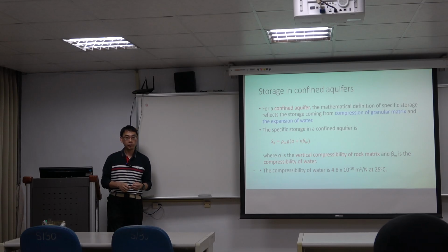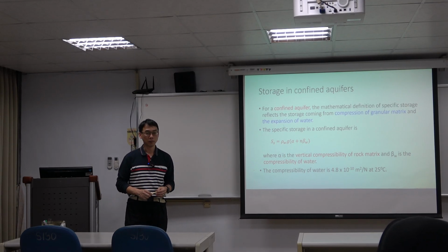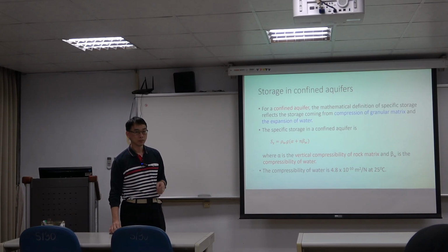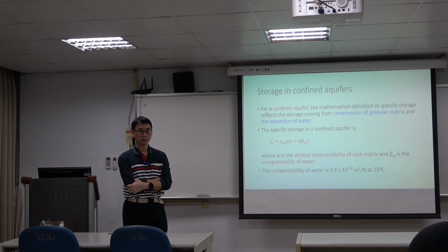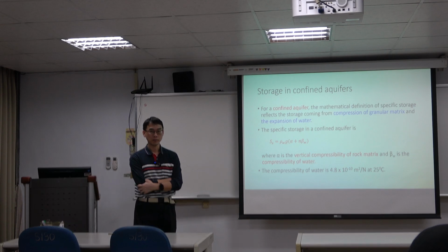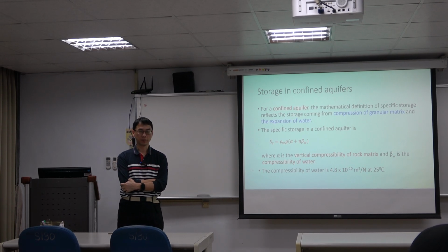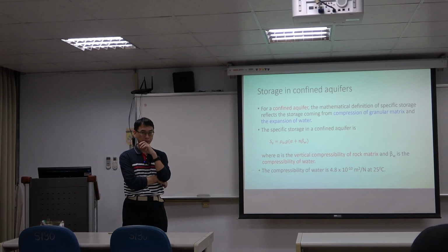Okay. I have a small question about the chemical and hydraulic properties. Because to obtain this value, you may need drilling. I'm curious whether the sample is disturbed during the drilling or because of the unloading effects, so the soil structure may be changed. So whether it's quite challenging to obtain from the samples.